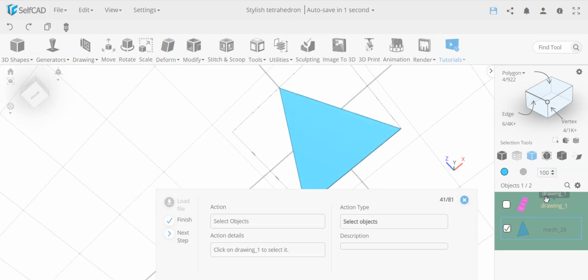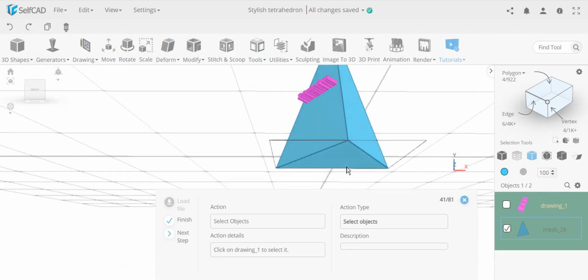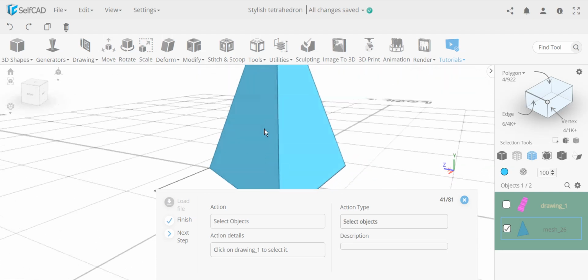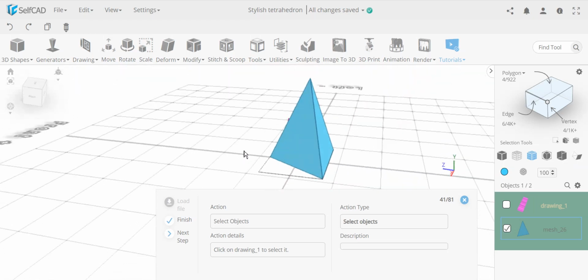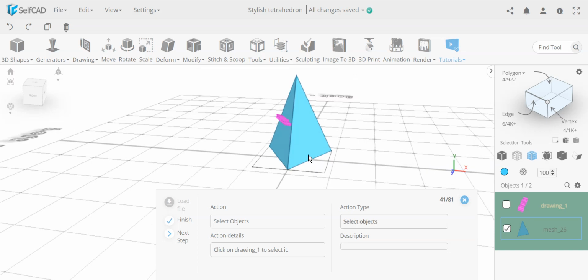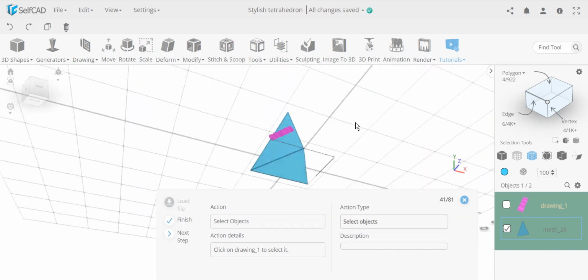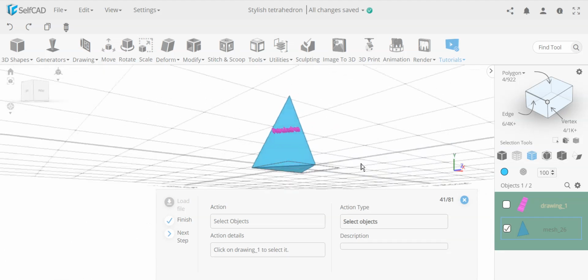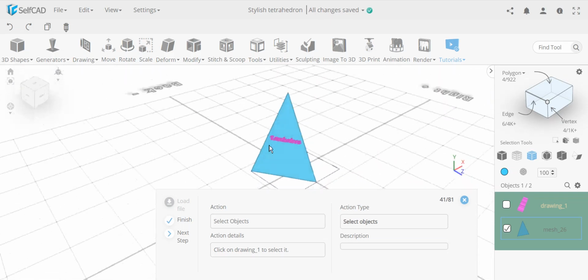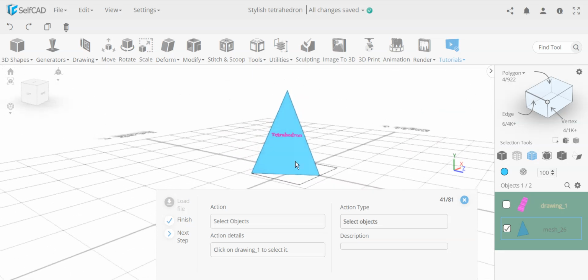At this point, before we make the cut, this text is still a separate object. If you think about it, we have one triangle at the bottom, and then 1, 2, 3 triangles that make up the sides. So we have a total of 4 triangles. And this is the smallest minimalistic shape that you can have in 3D that has a volume. When I say 3D, I'm not talking about measurement 3D. You can have a single face that you can measure at an XYZ position. That's not the point when you're talking about 3D. I'm talking about something that has a volume. The same way an area must be a minimum of 3 edges, a volume must be a minimum of 4 faces, or 4 polygon faces. Otherwise, it cannot contain a volume. So this is now the smallest shape that you can have.